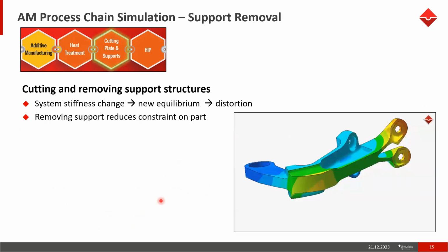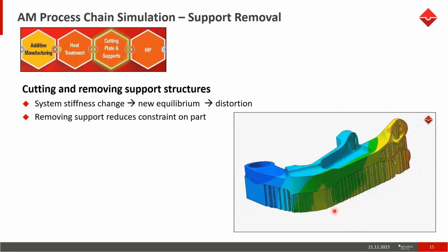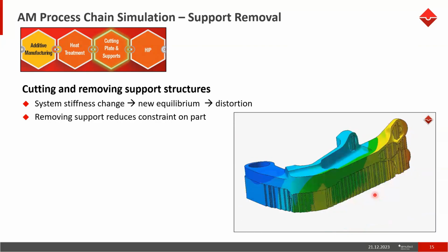And then comes cutting and removing. So cutting and removing is an important process. So you can see the animation here where the part is cut from the base plate and the supports are removed actually. So incremental cutting process can be simulated here in the SimuFact.